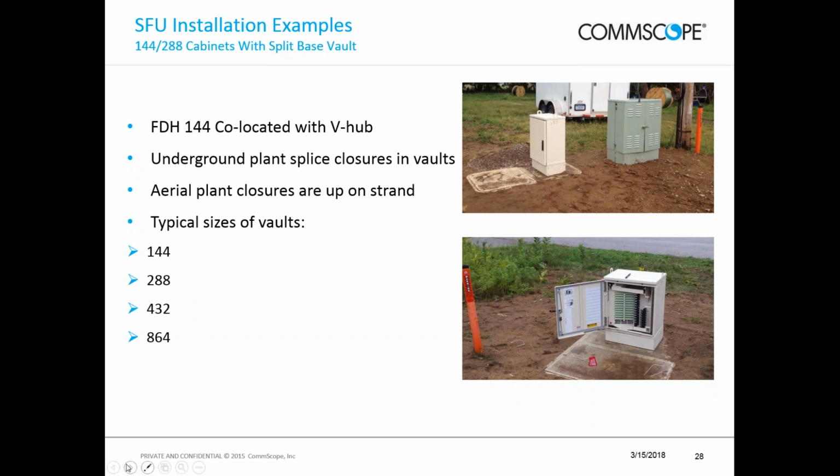Larry, looking at the FDH, is that integrally mounted on top of a vault? Because I've seen some vaults over the last 5 to 10 years where they're designed to have hardened structures on top of the vault, say a split vault, half of it's open, half of it's got mounting, or is this beside a vault? No, it's a split vault. Okay. And the FDH mounts on the one side, the hole's pre-cut and everything. You simply bolt it to the top of that lid. Yeah.